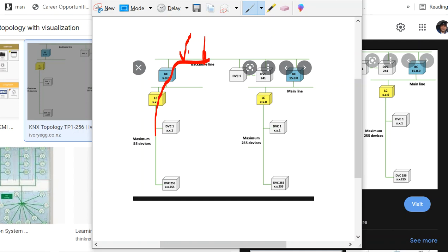But there is a better way. The better way is you see which group addresses you want to use here in the visualization, and then we add them manually to this filter table and this filter table, and you let the routing happen. Yes, this is what we do in the project, and of course in visualization we also mention that.